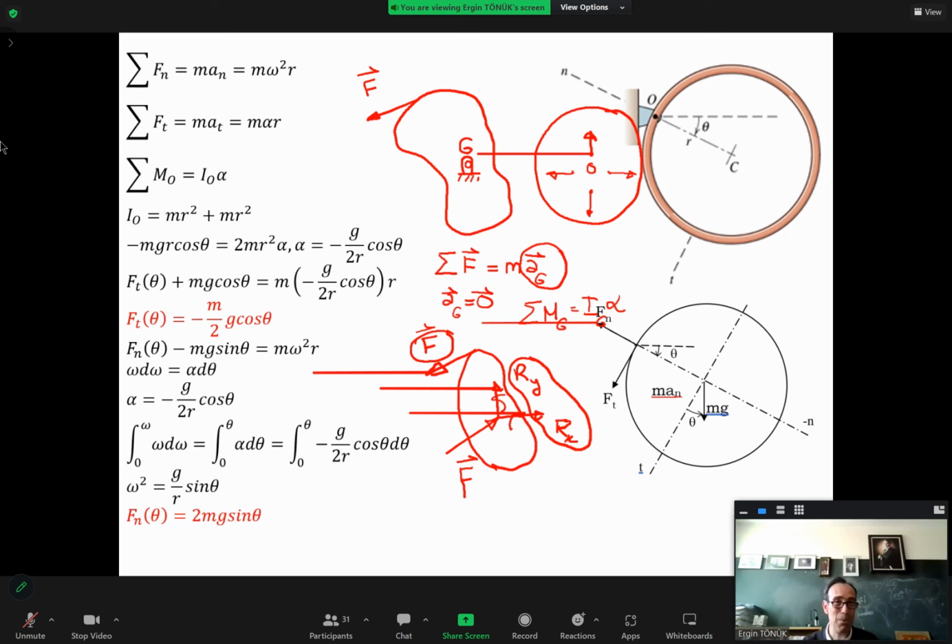Especially if it's in the front wheel, you will feel it in the steering wheel at higher speeds, and it's speed square dependent. Those centripetal accelerations are omega square r, so at low speeds, they would be small, but as you increase your speed, the magnitude of that shaking force is going to increase with the square of the speed, so you would feel really uncomfortable.